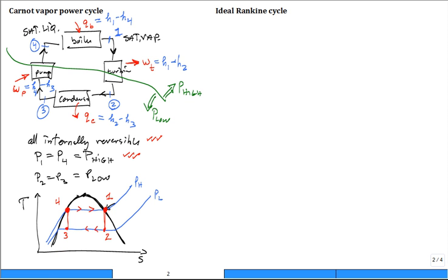And so here's our familiar box. What's that box? It's a rectangle on a TS diagram. That's how you get the Carnot. All of the heat transfer into the cycle occurs in the boiler, and it all occurs at what temperature? TH. All the heat that's rejected out of the condenser occurs at what temperature? All the heat transfer out occurs at TC.